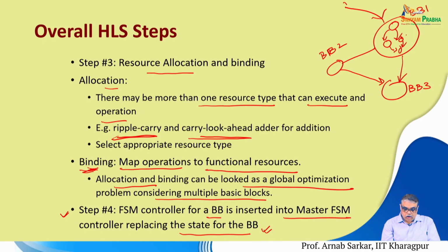When we have scheduled operations within the basic block and done allocation and binding, after that we can obtain the exact controller for the operations within the basic block, and this controller will be embedded within the master controller basic block node.